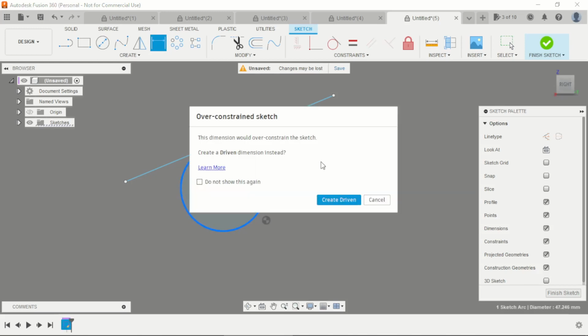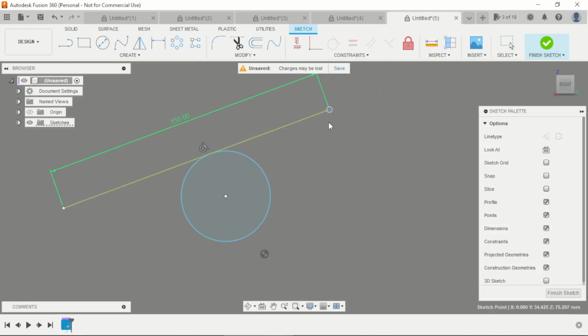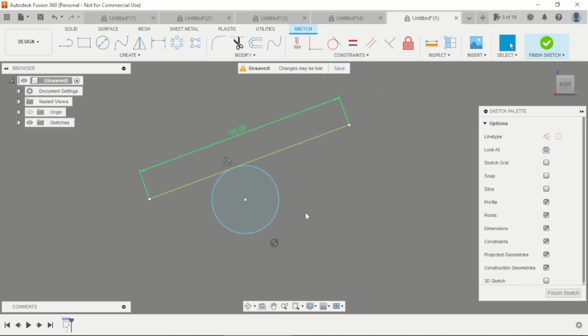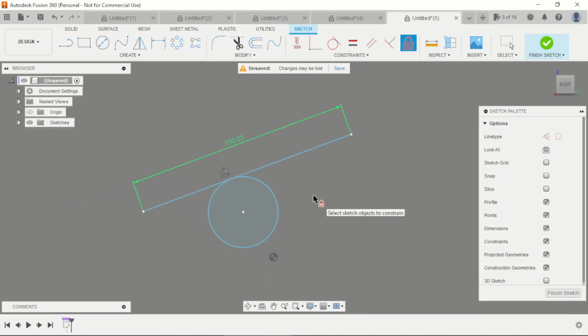And can't apply a dimension for this object that uses this constraint. To unfix the object, click on the object and click here. You can unfix that. Now it's free. We can apply it to the line. The line is fixed, but the dimension can be applied here. In this case, I can just move, but this is fixed in some axis. To unfix, click the line and return.